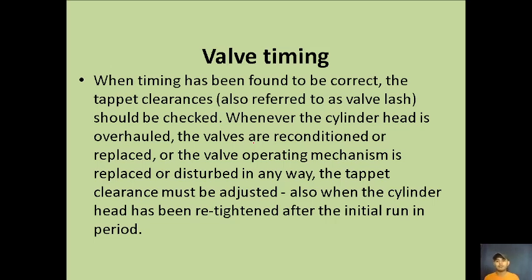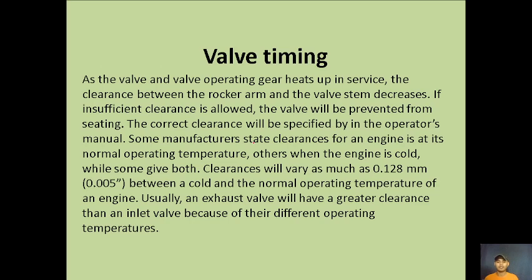Okay, so valve timing. When timing has been found to be correct, the tappet clearance, also referred to as valve lash, should be checked. Whenever the cylinder head is overhauled, the valves are reconditioned or replaced, or the valve operating mechanism is replaced or disturbed in any way, the tappet clearance must be adjusted. Also, when the cylinder head has been retightened after the initial run-in period.